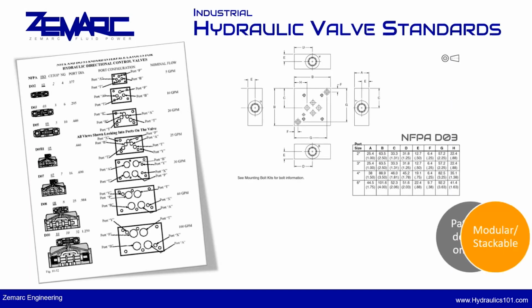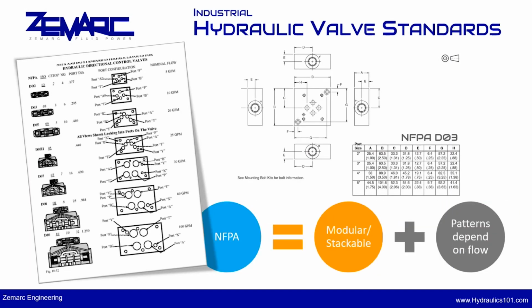All right, so as I mentioned earlier, there are specific standards with hydraulic valves, pardon me. Now, when you deal with certain valves, for example, industrial hydraulic valves, you run into certain standards for how they mount and the flow and pressure they are able to handle. That information would be found in the likes of the NFPA and ISO interfaces, which is things related to the NFPA D03 standards.